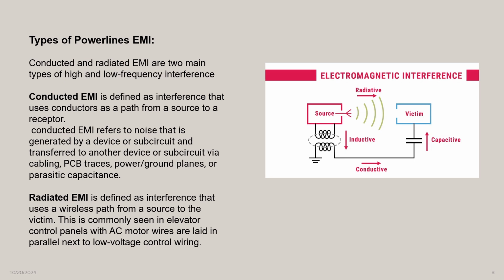For example, a motor encoder grounded to a noisy connection conducts noise to the drive encoder interface. The conducted noise would cause the drive encoder interface to receive inaccurate voltage signals, preventing the elevator drive from interpreting the motor speed correctly or causing drive faults.